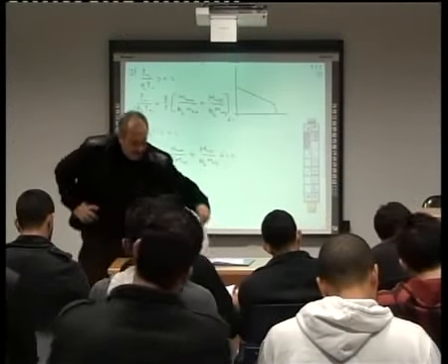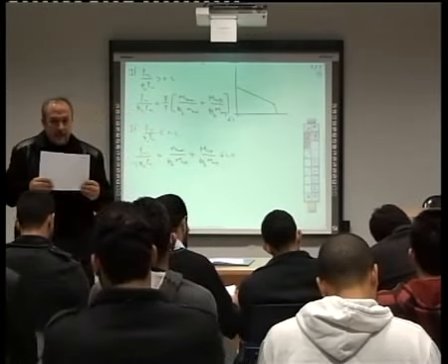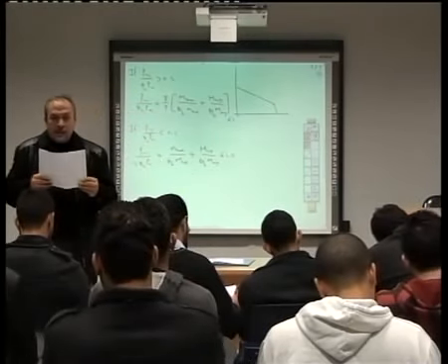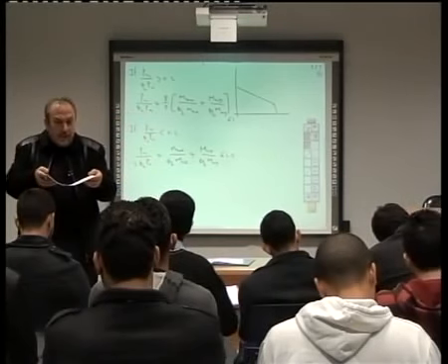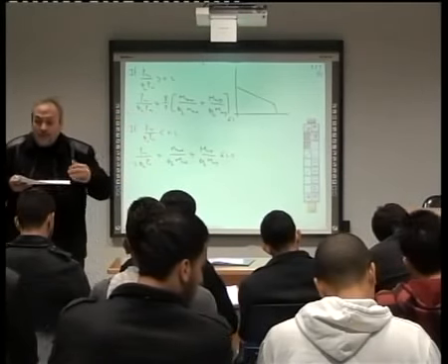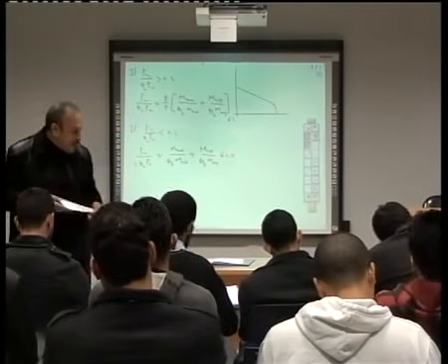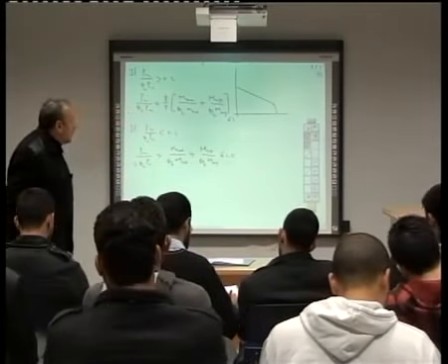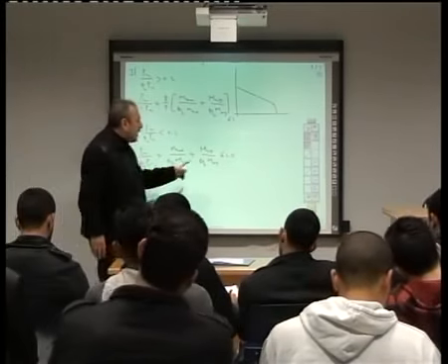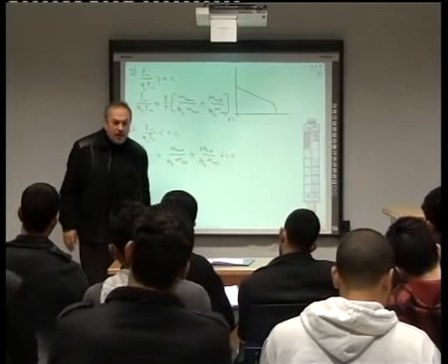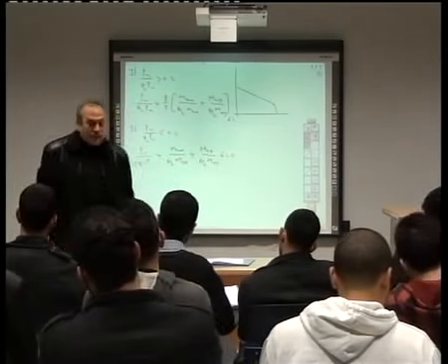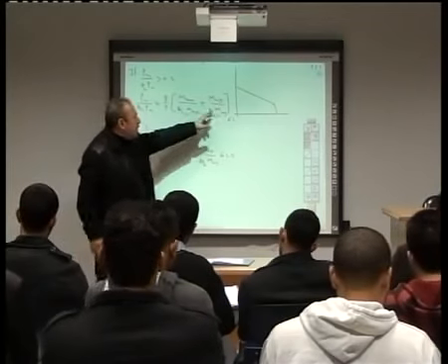Why? Because when the member is like this, it can go like this in lateral torsional buckling. But when the member is like this, when you put an I section like this, it will never go into lateral torsional buckling. Many students, unfortunately, we bring a question that the bending moment is around the y-axis, and he starts doing calculations of lateral torsional buckling. You are wasting your time. So this and this already known.